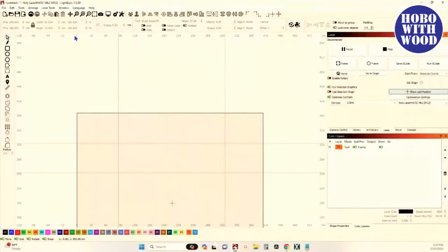But this one thing that I've noticed, guys, whenever you use these guidelines, when you drag it down, watch up in the X and Y position whenever I bring this in, switch over. When you first grab a line and you start dragging down, X and Y position is not active. It's not working. As soon as you drop it, though, and grab it again, now it's active. And you can position it exactly where you want. Say, okay, well, I want that at 360. Okay, drop it at 360. You can also just enter those in manually.